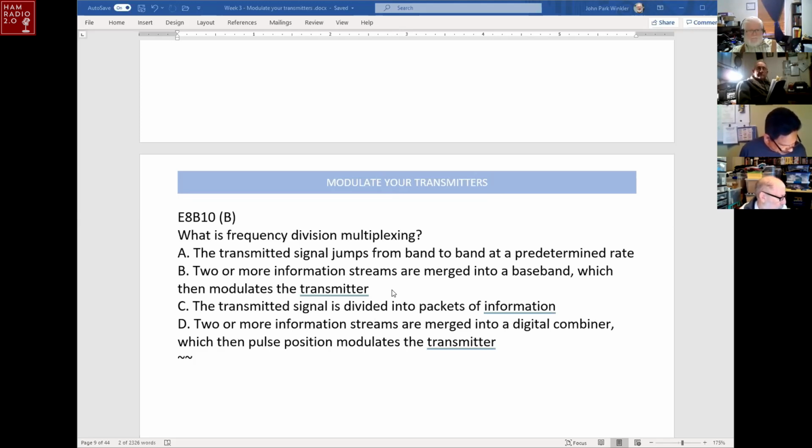Okay, so the SCA carriers on a FM broadcast station would be another example of that frequency division multiplexing. Yes, exactly. What they do there, gentlemen, is they transmit agricultural information or pipeline information or whatever on the same carrier as a broadcast FM by using a subcarrier that is, I believe, somewhere around 90 kilohertz, which is above anything that the FM audio is going to deal with. And FM stereo does a similar thing by using subcarriers to transmit the left and right channels.